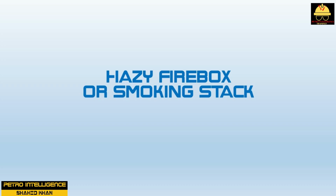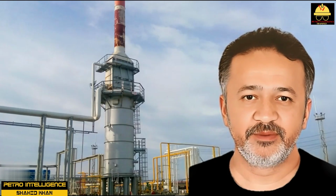Broken supports and guides. Broken supports and guides tend to fall to the furnace floor and result in sagging or bowing tubes. The falling supports and guides can also hit and damage a burner. Hazy firebox or smoking stack. Hazy fireboxes often occur when insufficient excess air is going into the firebox or the fuel-air mixing ratio is incorrect.